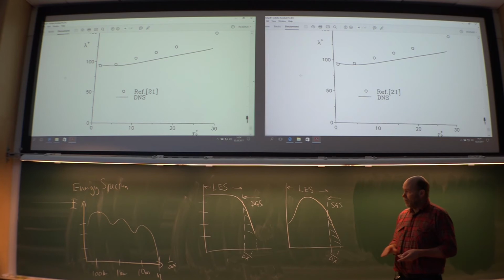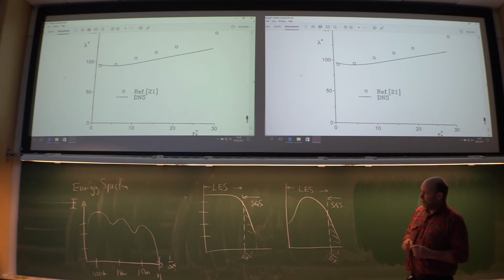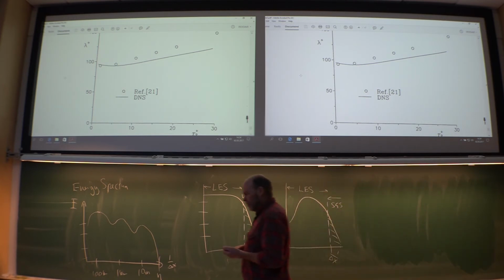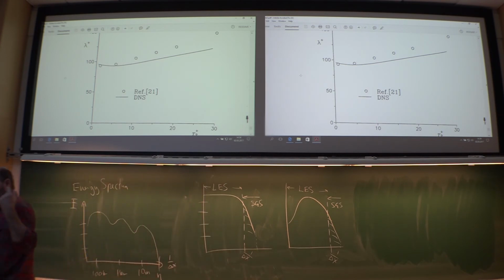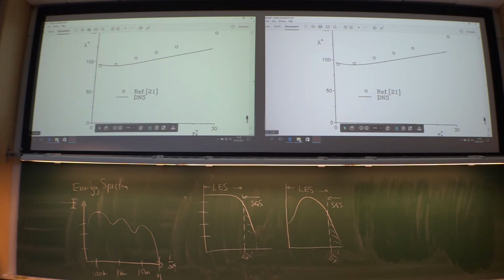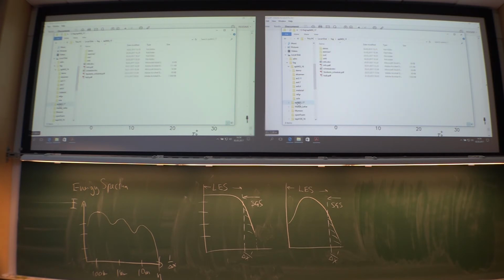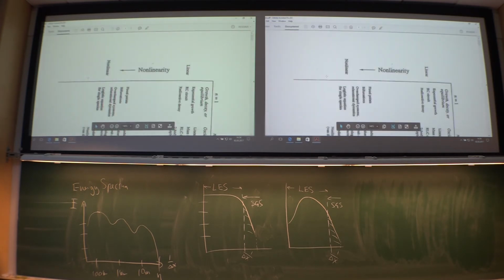So they can actually do a fairly decent large eddy simulation now with quite high Reynolds number, but it's very expensive indeed. But in order to get good results, remember the nature of turbulence. It's three-dimensional, it's transient. So with LES, you still have to use full three-dimensional codes, and it must be transient as well.